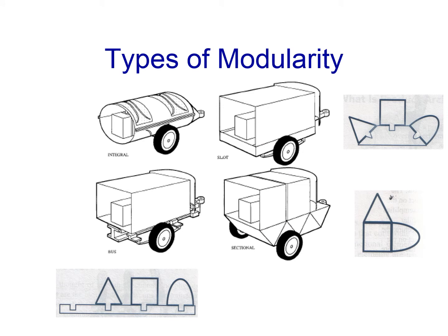There are 3 types of modular architectures. All have one-to-one mapping between functional elements and physical chunks. However, the difference is in the way the chunks interface to each other. For example, in the slot modular design, all chunks are attached to a bus module, but the interfaces for these modules and the bus are of different type. Notice that this is a triangular interface, square, and a different interface here. You cannot interchange them. A radio and climate controls in an instrument panel is a good example of that.